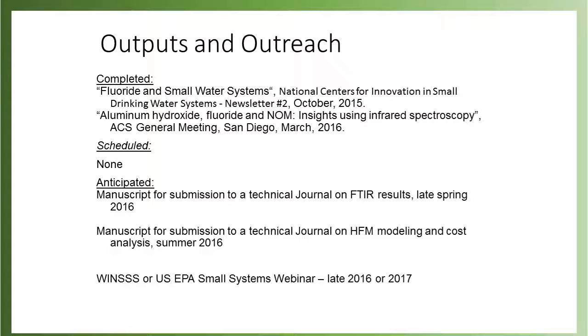So, how about other solutes? Well, in the electrode rinse, you have to be careful. You can't use chloride-based things, or you can get chlorine. With the ambient chloride, it's low enough that it's not a problem. And other reactive oxidant species? I haven't really looked at it in detail, but I don't think so. It's all happening at the electrode, and you're supplying the electrode rinse water separate from everything else, so you can pretty much avoid that in any system. It's a really small stream that can be recycled even in a full-scale system. So I don't think that's a big issue.